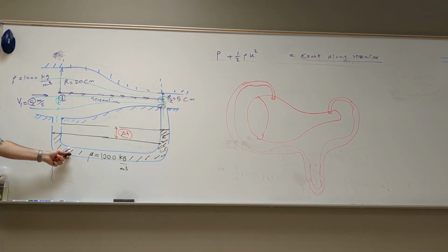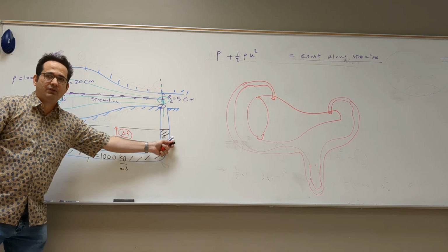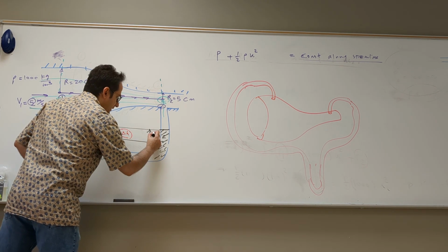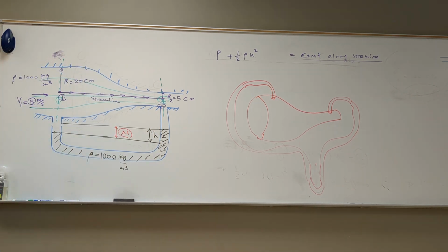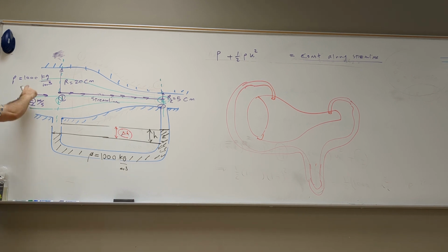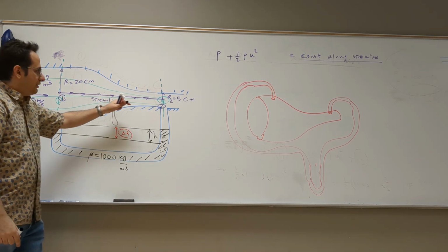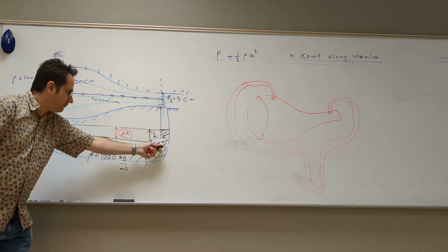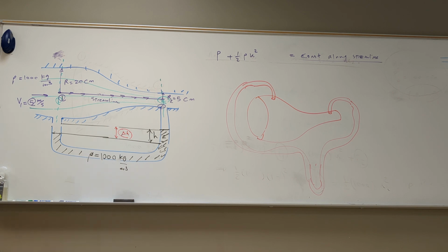Now take this fluid. They usually use mercury for this fluid, but because it may be dangerous, let's take just water, right? This is the height of the water, and I want to compute it. That means if I go to the lab and build this nozzle and put the fluid velocity and density here, and I measure velocity here, or I use continuity to find velocity here, then what is my delta H? Now this is the problem.